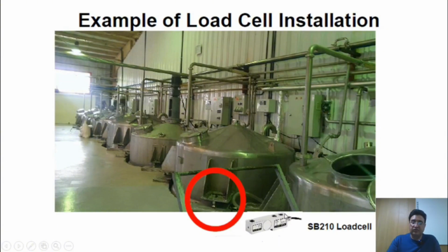Ultimately, these 4 load cells are all connected together to a central summing box, also commonly referred to as a junction box. From this summing box, a single output signal is taken and connected to a weight indicator, which is a crucial device. This arrangement allows us to accurately see the weight contained inside these large tanks, displayed on a digital display. This final part of the system pertains to the weight indicators, which provide the measurement readings.